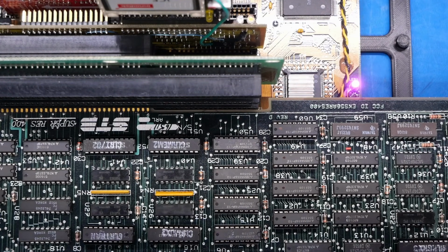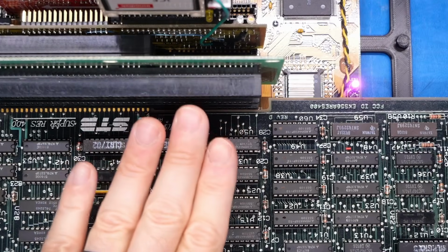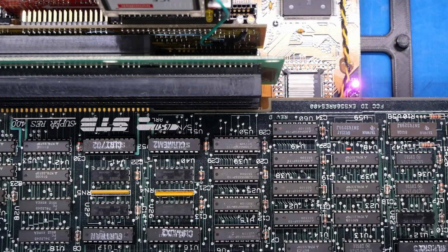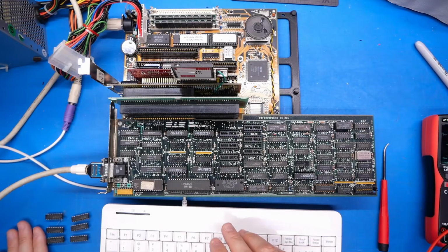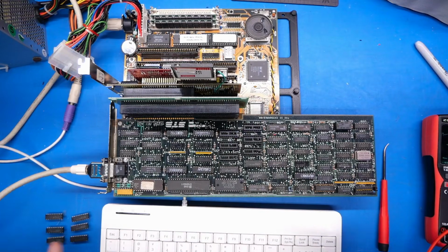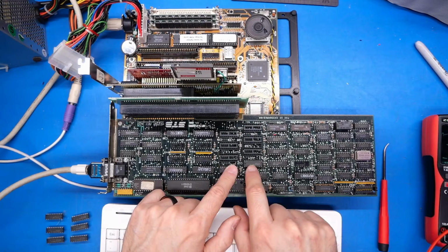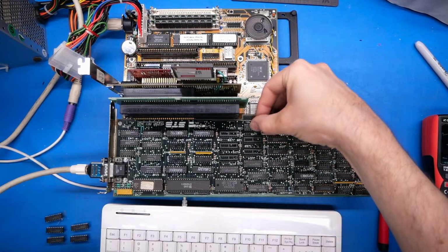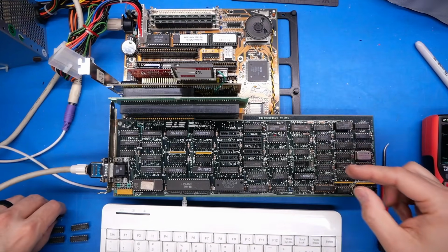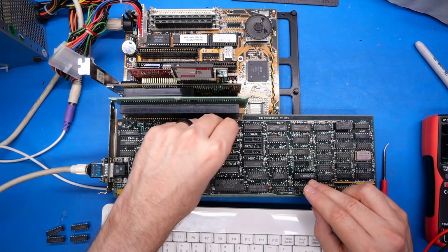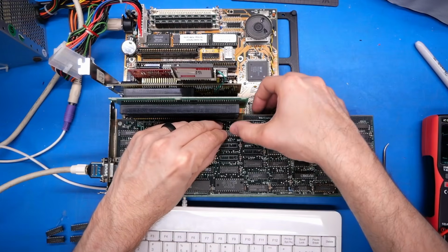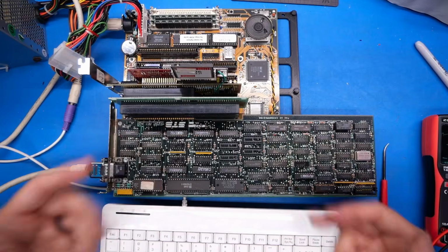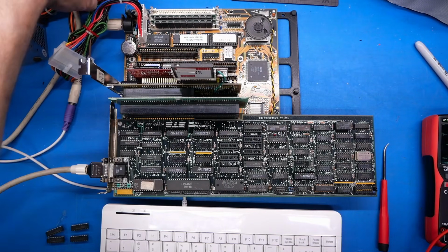I think the first thing I want to do is start taking these chips out and seeing when we start having broken video on this machine. Okay, here are the chips over here. They're taken out exactly the same way that those were in there. Let's see if this card works with just these two chips installed. All right, here we go. No. So what I'm going to do is install these bottom chips here. I want to see if this brings the card back. And maybe these are the ones that are actually in use on this card for regular CGA mode. Let's just turn this on and see if it beeps.